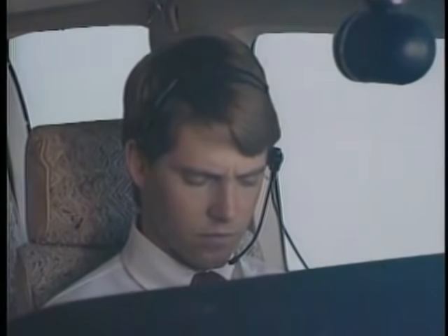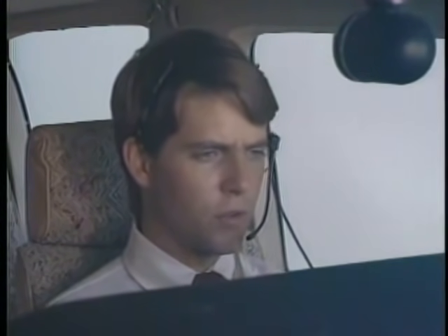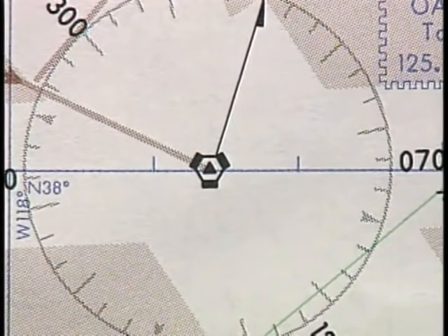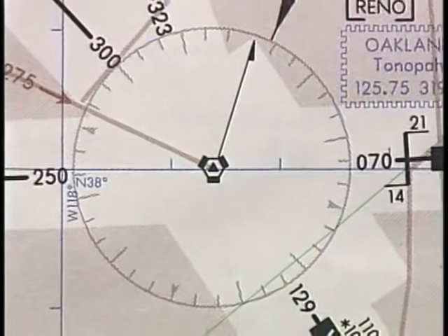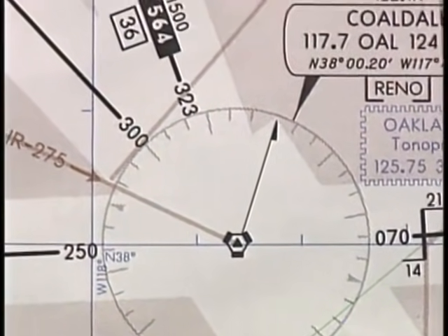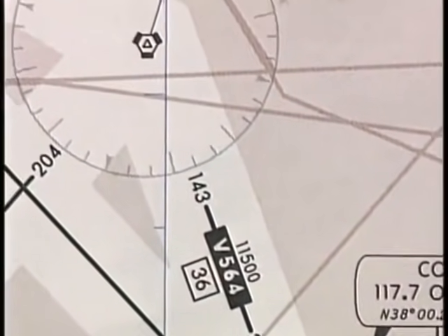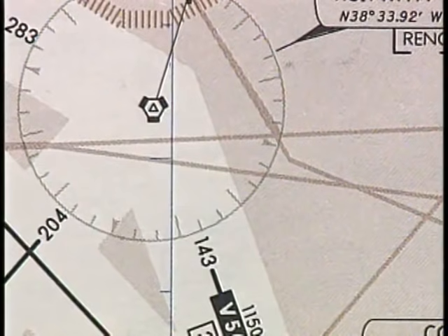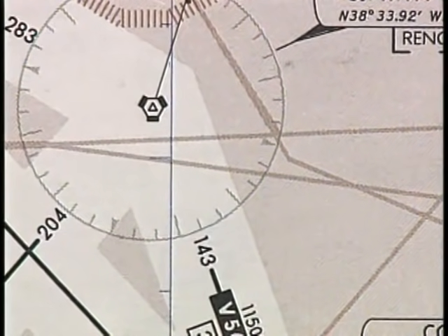Unless you are in radar contact, IFR position reports are required at certain points along the airway. These points are referred to as compulsory reporting points and are indicated by solid triangles. If the compulsory reporting point is at a navigation facility, the solid triangle will be a part of the facility symbol. Open triangles depict non-compulsory reporting points requiring a position report only when requested by ATC.